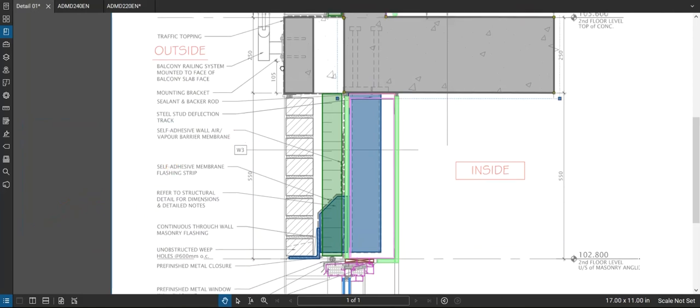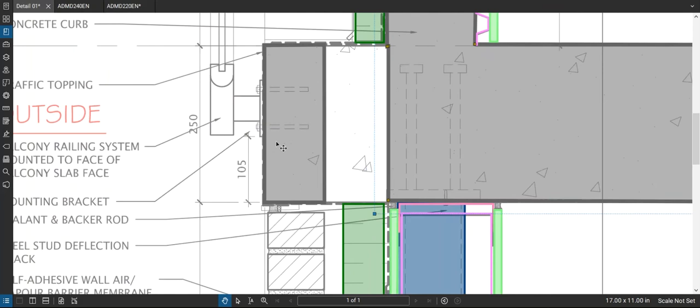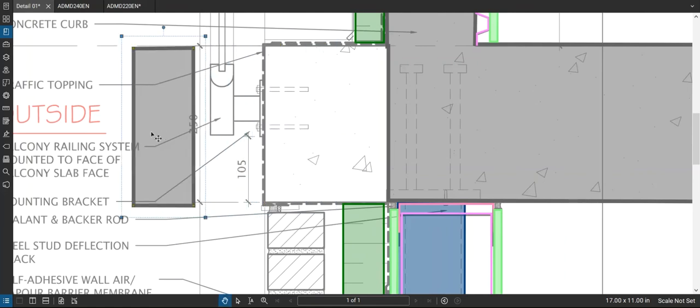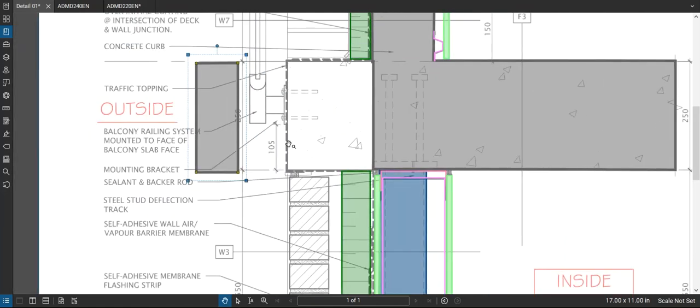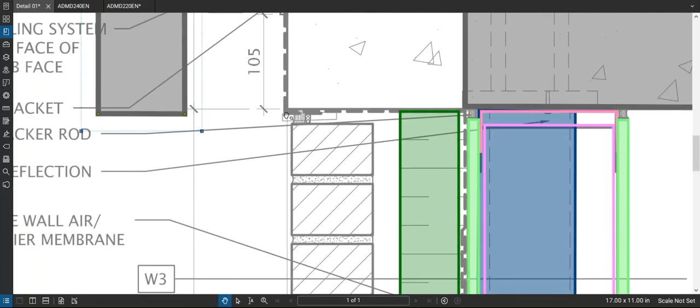But I wouldn't be done there. There's still problems with this concrete. So one way to step this up a notch is, and actually let's take a look at the picture because probably this is happening. With the concrete coming out to here, there's a ledge here. This ledge is going to collect a bunch of dirt and grime. It's going to rain, it's going to snow, and melt is going to happen, and it's going to run down the face of this thing right here, and stain down the front of here, going right onto the brick surface and staining the brick.